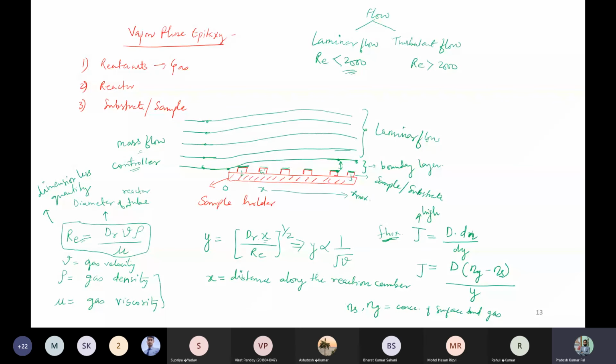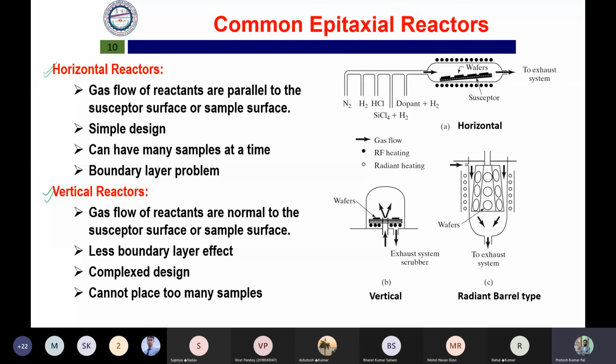Okay, so it is a very simple design. In the previous design, initially, this was the surface on which we put the sample and we flowed the gas. The gas flow was such that here it was receiving a better deposition, and here a poor deposition of the epitaxial layer. So to avoid this, the support, the holder we have placed there, is used in a modified form, like a tilted or inclined form.